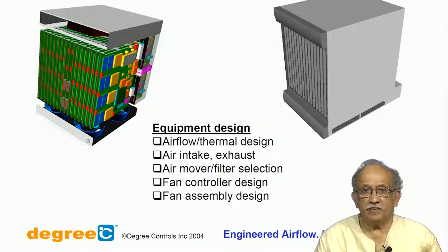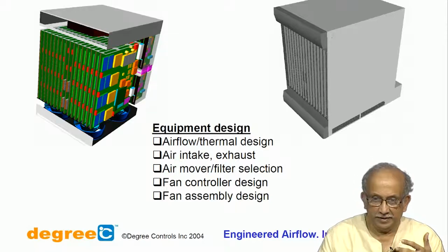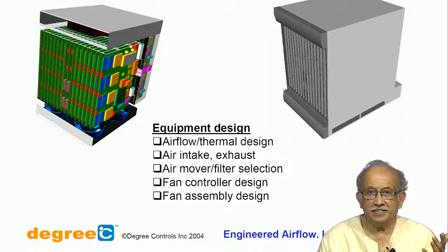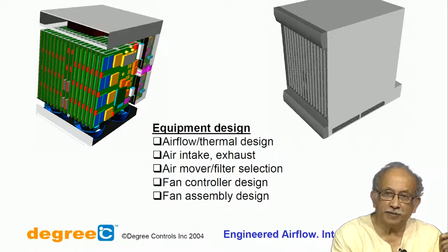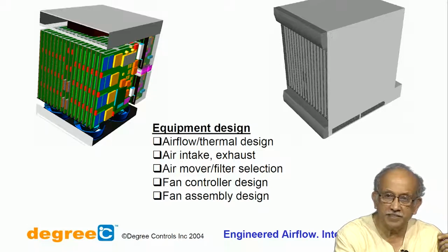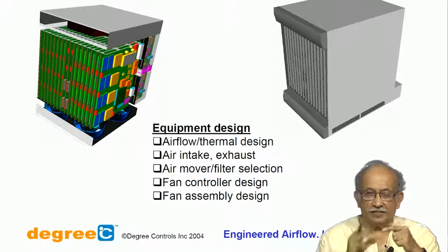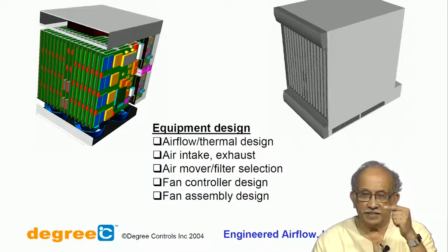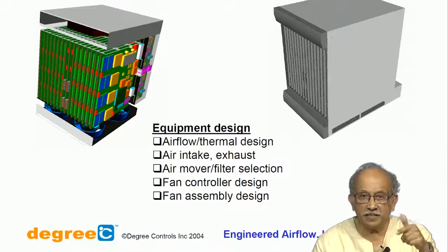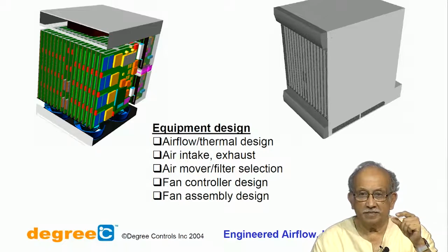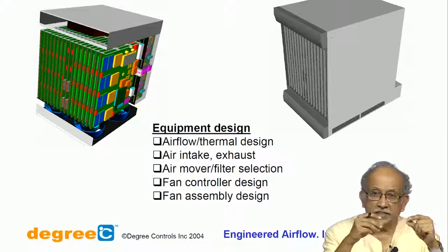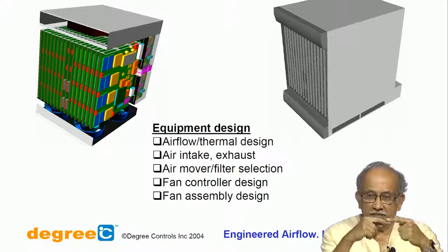So, in large racks where you can afford to have this, all of these things are used together. So, you have a vane switch, then you have a standard pressure sensor, and then here you have a temperature sensor. Usually something called a Curie switch is there. There is a magnet where the Curie point is adjusted to a critical value. If something exceeds around 80 degrees centigrade, automatically it changes state, it loses its magnetic field. So, that whole thing is probably put on a reed. You have seen the glass reeds.